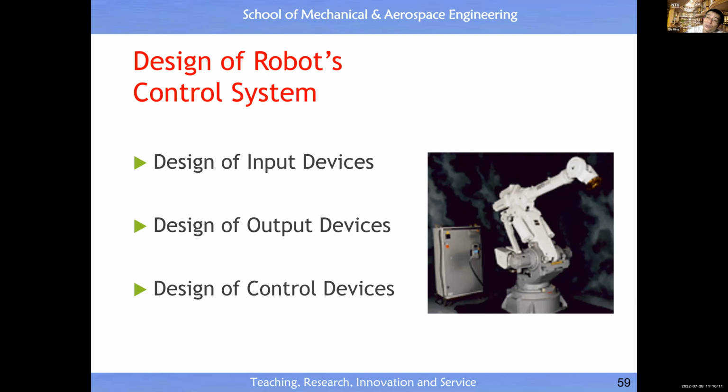Inside the feedback control loop, there are only 3 important modules. One is input, which is a sensory device. Second one is actuator, which will produce the output. And the third one is a controller, which will make a decision based on the error. You remember, when error is not 0, take action until the error becomes 0, right? So there are 3 basic building blocks inside a control system, okay? The input sensory device, output actuation device, and the controller, which makes a decision, all right?